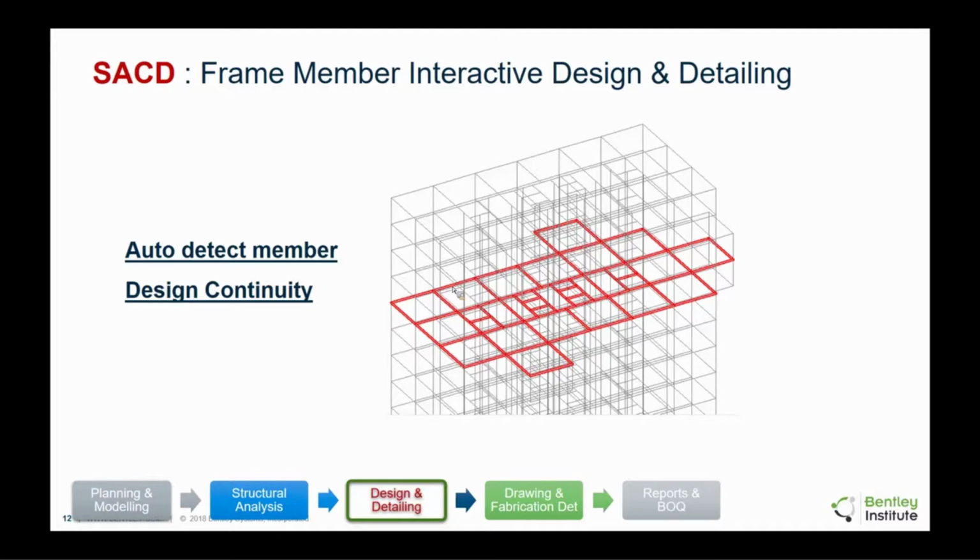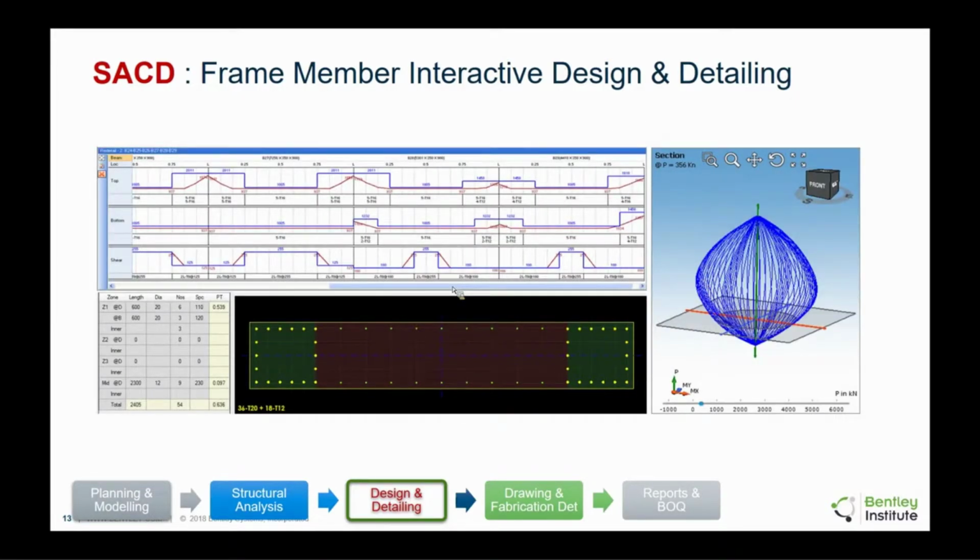Another amazing feature is the software will design, detail, look at optimization and give you an output. And I think the biggest concern, what we don't like about a lot of software, is that it gives you an output, but if you disagree with it, if you want to make changes, you need to go offline and use an Excel sheet or do it manually and so on. And that's where here it's completely different. You can completely change everything. You can change member sizes, material properties, rebar arrangement, whatever you want. The software will check for all sufficiencies during runtime, and if required also gives you an option to go and update the member sizes back in the STAAD file. So it completely manages the change that you make.